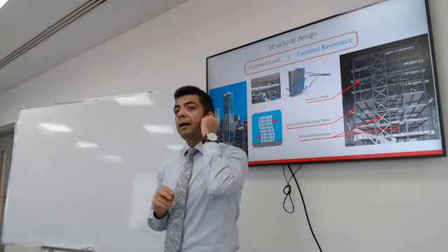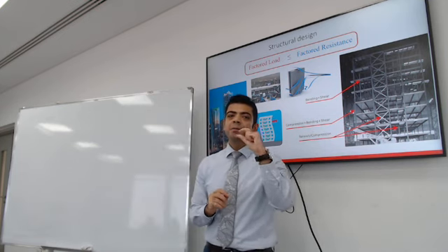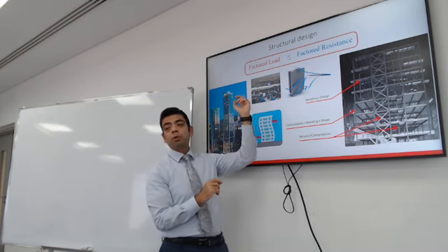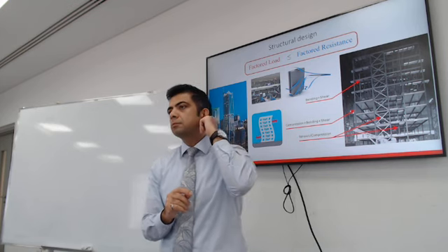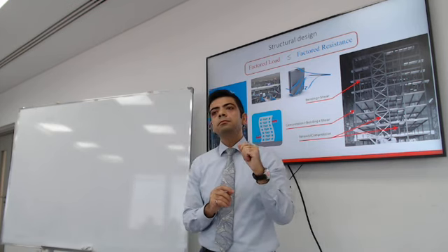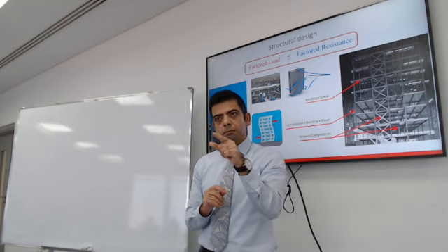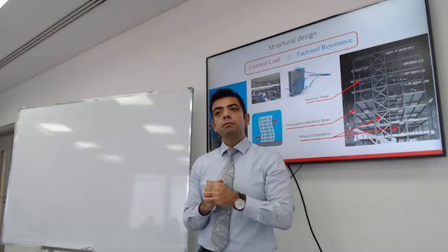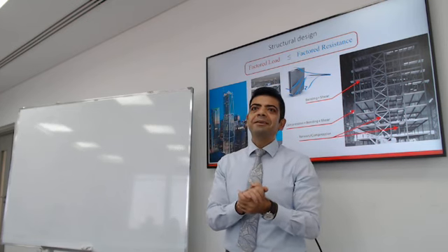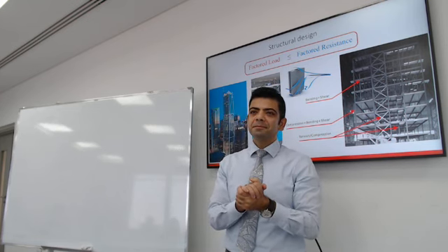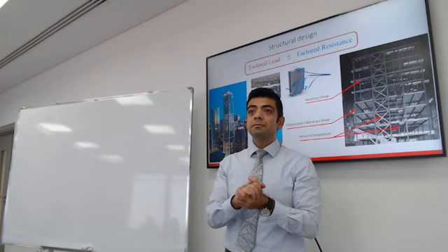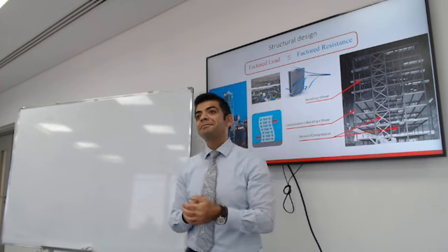So, how do you choose the beam? What beam is good enough to support the weight of this floor? The moment and the inertia and everything you've calculated, you see which one applies in your section. In the tables, you see what's the best option to withstand all of it. For example, if you have a moment of 82 and you have one that's 80 and one that's 83, you're not going to take the 80, you're going to take the 83.